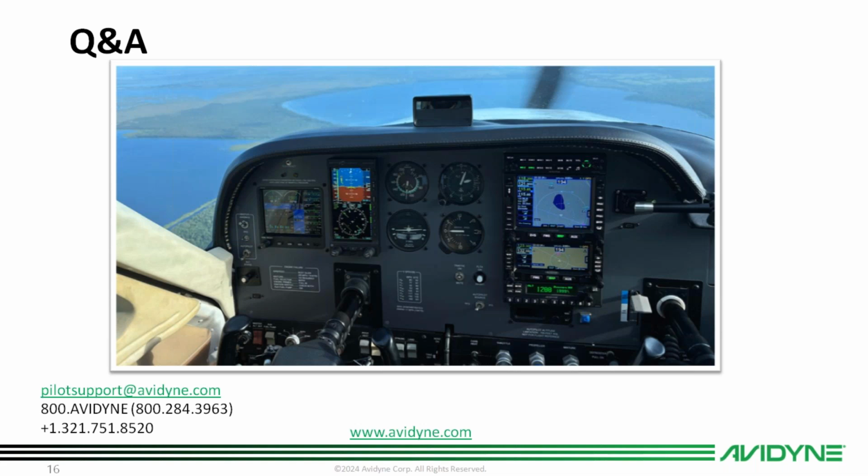Is my FlightStream 210 worthless with my IFD 440s, or will it talk to them? No more FlightStream 210 or 510. Because the IFDs have that capability already built into them, there's no use for the FlightStream devices. So I wouldn't say worthless, but you could certainly sell it, because it won't do you any good in that airplane if you have full IFDs.